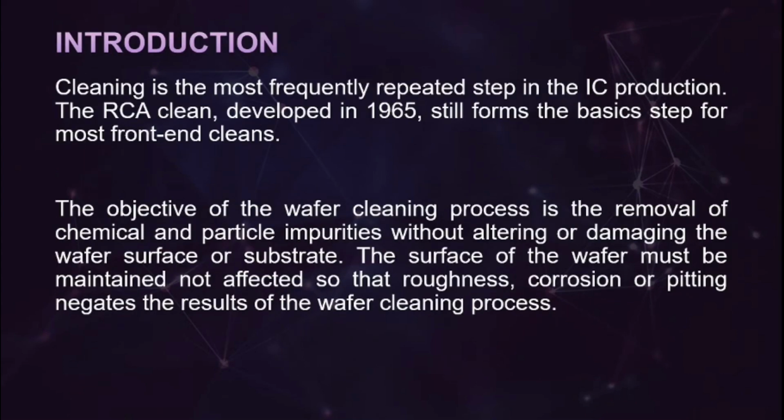First, introduction. Cleaning is the most frequently repeated step in IC production. The RCA clean, developed in 1965, still forms the basic step for most front-end cleans. The objective of the wafer cleaning process is the removal of chemical and particle impurities without altering or damaging the wafer surface or substrate. The surface of the wafer must be maintained, not affected, so that roughness, corrosion, or pitting negates the result of the wafer cleaning process.